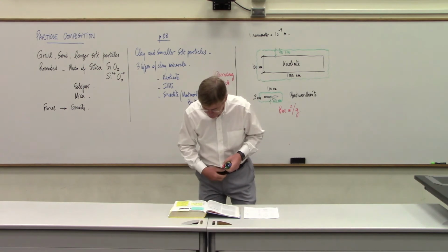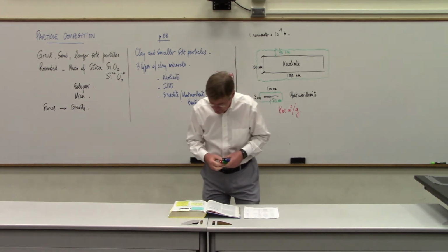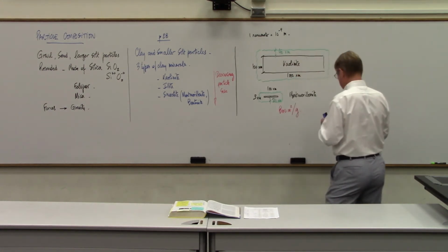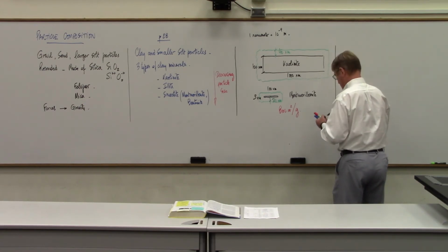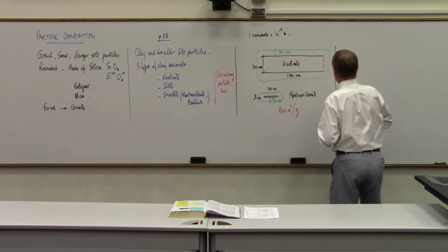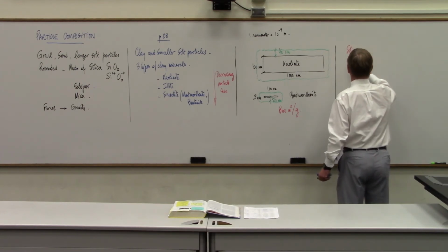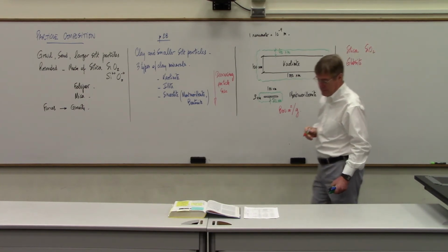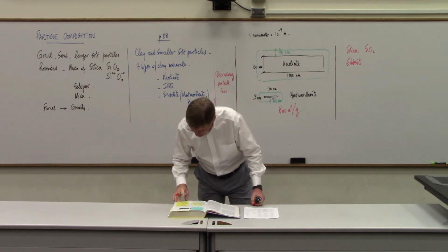So that's in terms of size. The minerals themselves are made of two types of, maybe I'll add it here on this side. The minerals themselves are made of a sheet of silica and a sheet of gibbsite. So silica, I told you, SiO2, and the gibbsite, I don't know it by heart. Where is the gibbsite in here? Al2(OH)6.